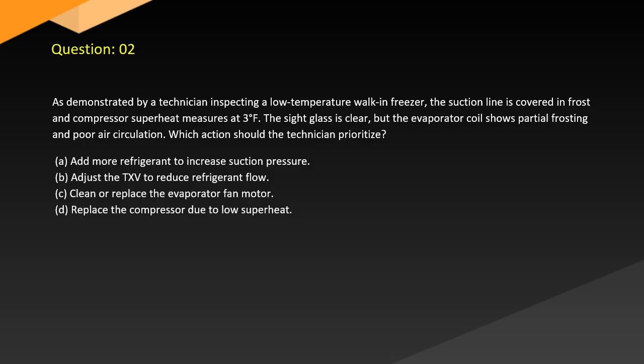Question 2. A technician is inspecting a low-temperature walk-in freezer. The suction line is covered in frost and compressor superheat measures 3 degrees. The sight glass is clear, but the evaporator coil shows partial frosting and poor air circulation. Which action should the technician prioritize?